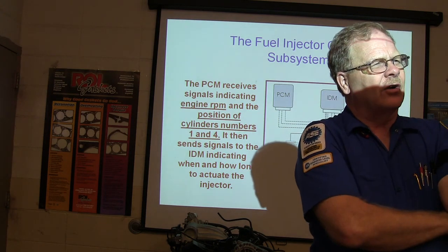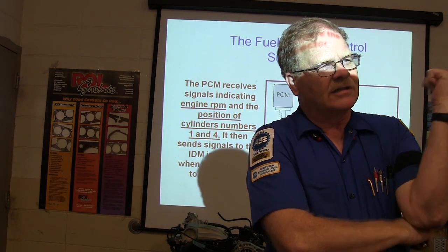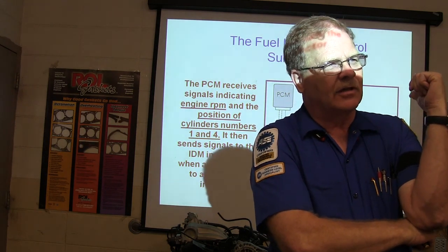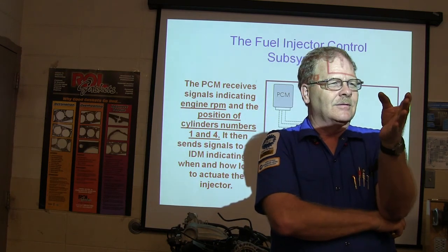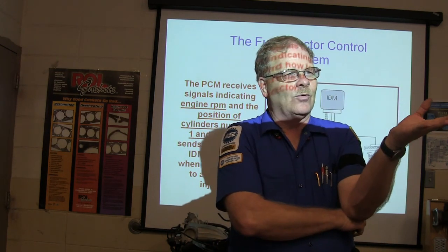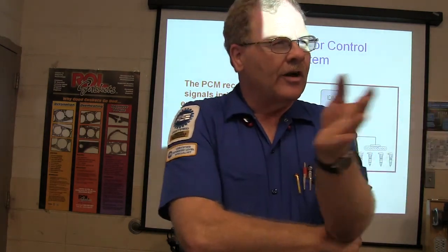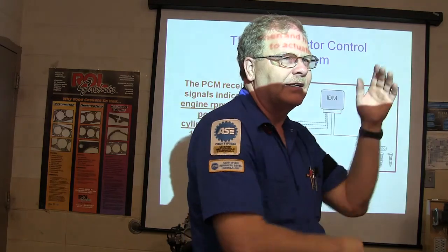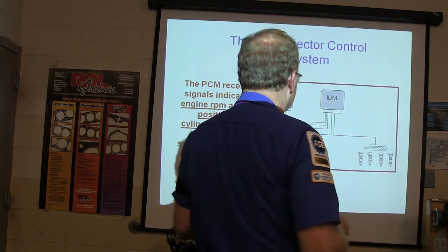Now this one right here, the cylinders are numbered different than a regular Ford vehicle because this was made by International, Navistar International. But if you looked at the pattern of the firing order, this 7.3 has got the same firing order pattern as an old Ford, 154266378. But the cylinders aren't numbered the same way. You see what I'm saying? Because the cylinders are numbered different, the firing order's actually technically different.